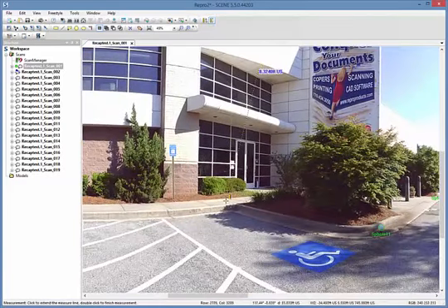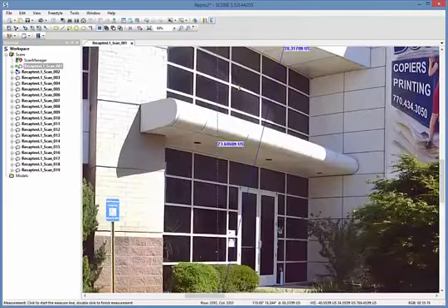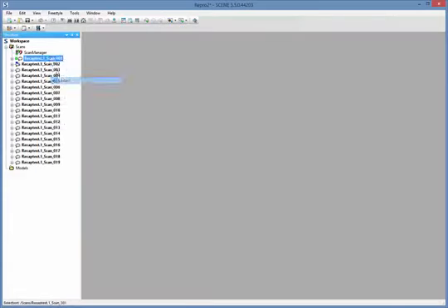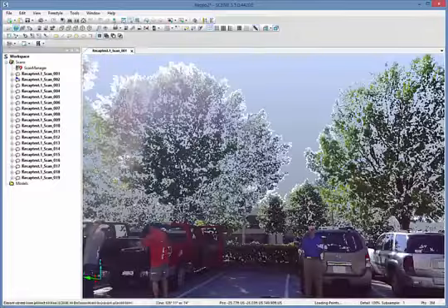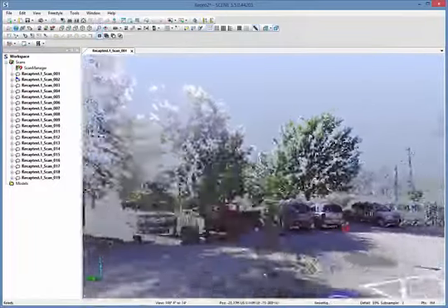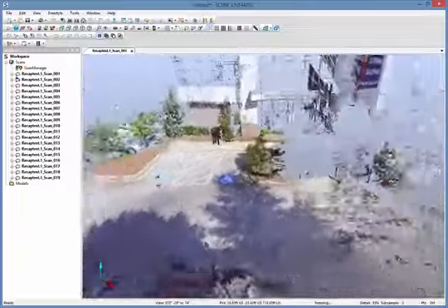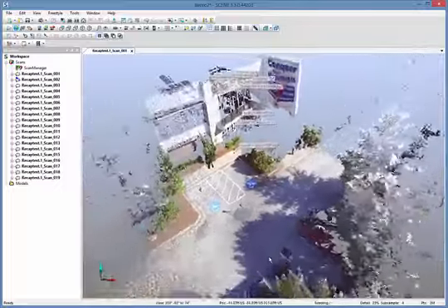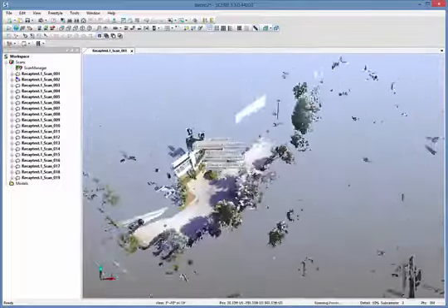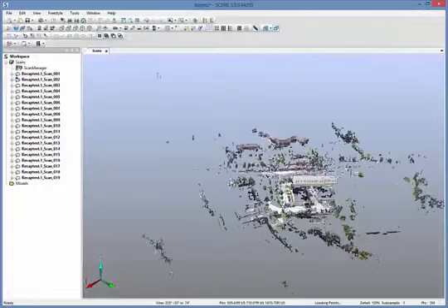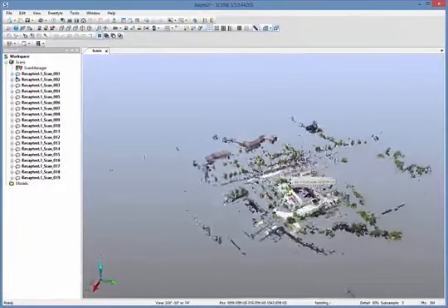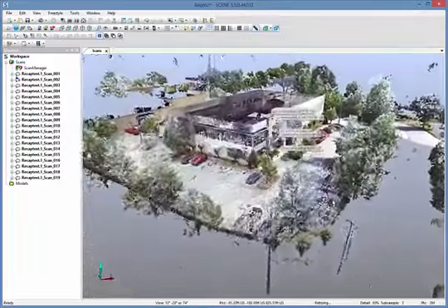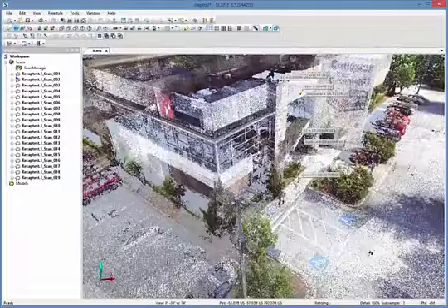When measuring from the floor to the ceiling, the dimension is broken out to give us the true vertical measurement. Now we are no longer looking from the point of view of the scanner, but are looking at the true three-dimensional point cloud of the captured data. As we zoom out, you can see the amount of data that were captured from just a single scan location. After all of the scans have been registered together using the targets that were placed in the field, the complete point cloud can be seen. From here, we can export the point cloud to our downstream applications for use in planning and design.